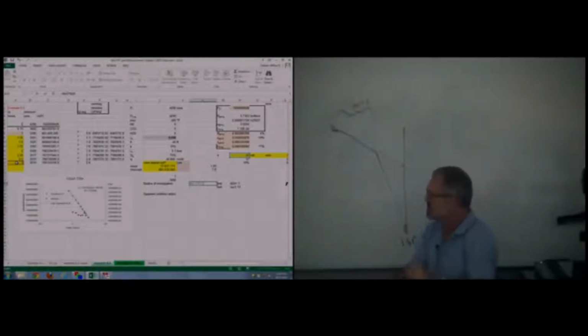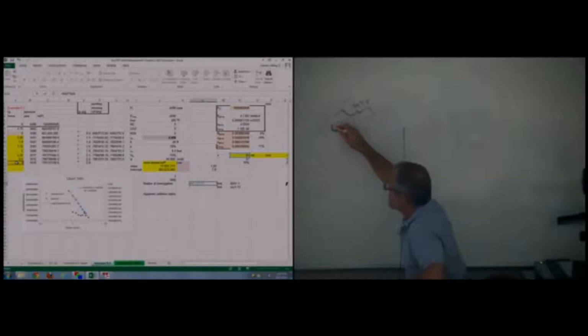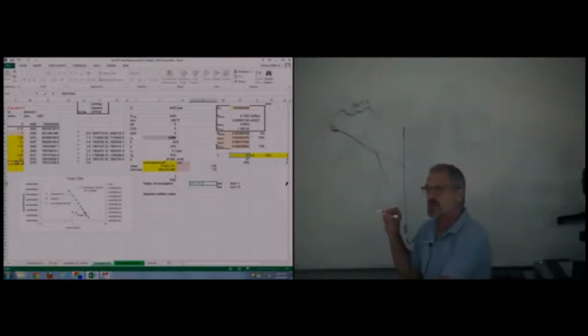Now, I've got this drawn as a buildup rather than a drawdown. In a situation where our data deviates from the straight line, we wouldn't use the last test point time. We would use the last time that we're still in the middle time region.